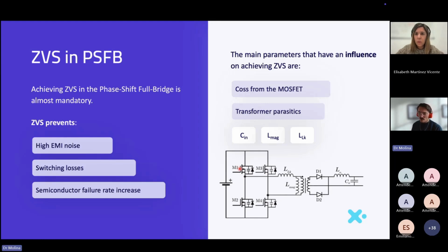I'm not going to go that deep, because for me, it's just to explain that if you go to a MOSFET data sheet, any MOSFET from, let's say, Infineon or Texas Instruments or whatever company, you will need to find the values of the parasitic capacitance. And in this case, this is the typical one that we use for this calculation, that is called COSS.